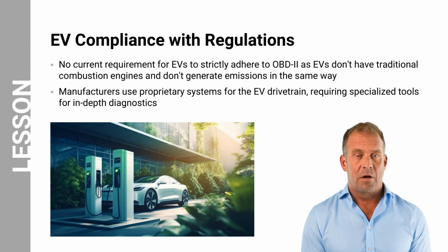However, for purely electric parts of the EV drivetrain, battery, electric motor, etc., the information accessible through OBD2 might be limited. Manufacturers use proprietary systems for these components, requiring specialized tools for in-depth diagnostics. Currently, OBD2 functionality in EVs is a mixed bag. It can be helpful for some issues, but may not provide complete diagnostic information. The future looks like there will be a more standardized system for EVs, but it's not quite here yet.